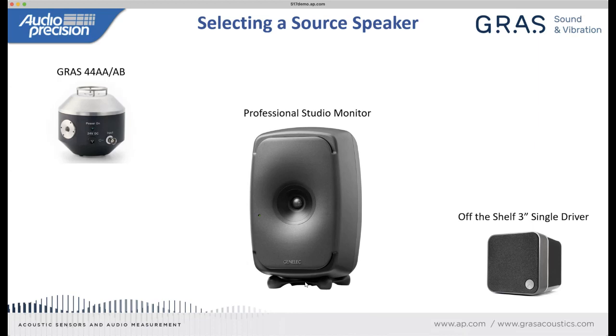I'll talk a little bit about the practical side of using a source speaker when we talk about equalizing it. But generically, what we're looking for is a speaker that can generate test signals over the frequency range of interest and at the acoustic output levels that we're interested in testing at.